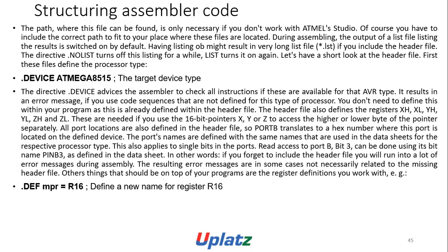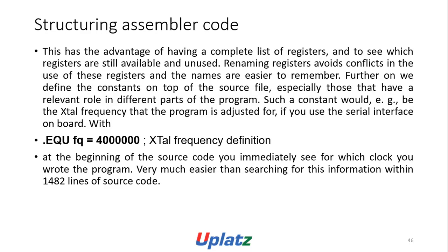Other things that should be on top of your programs are the register definitions you work with. Example: .def MPR = R16 ; define a new name for the register R16. This has the advantage of having a complete list of registers and seeing which registers are still available and used. Renaming registers avoids conflicts in the use of these registers, and the names are easier to remember.